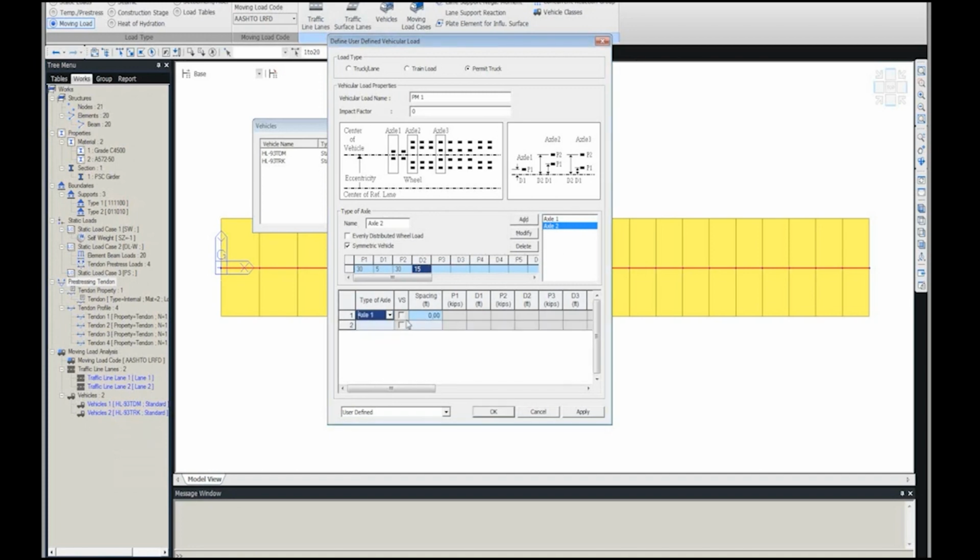You can select the spacing between this axle and this next one, and if you have a varying spacing, you can simply model it here. Here we have only 2 vehicles, so it doesn't let me check it. Oh, okay. Now we can get this, and then let's say spacing is from 20 to 50 feet. So that's the way that you are modeling.